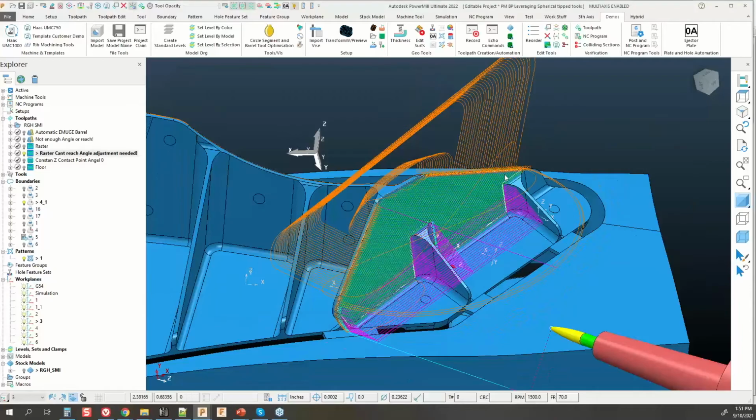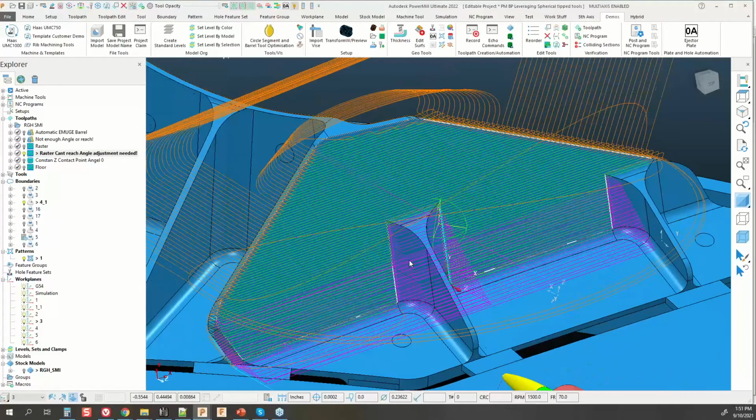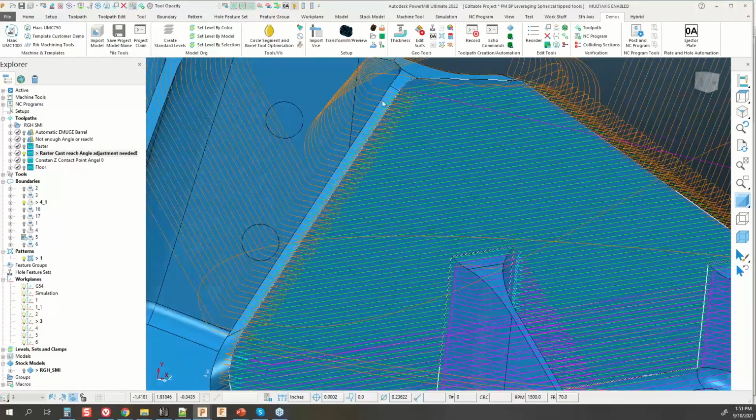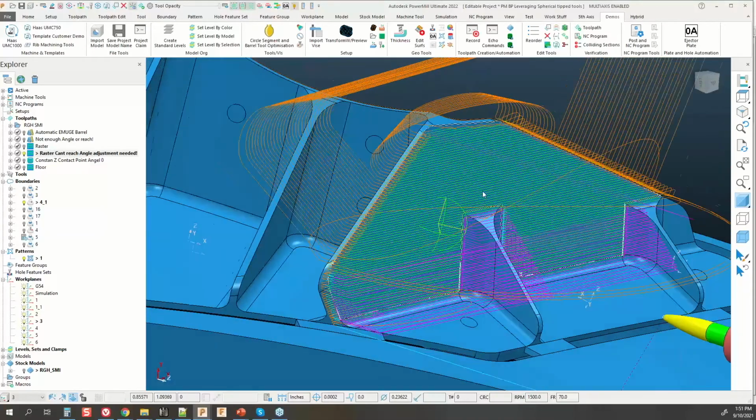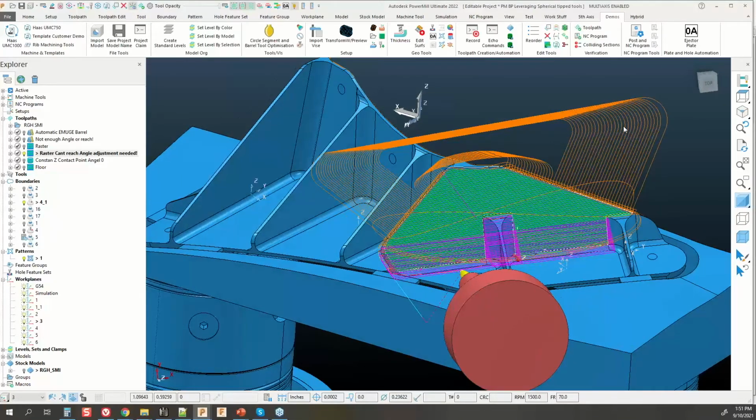Now you'll notice there's a lot of chaff in this toolpath. There's a lot going on here, things that I'm not going to want from the calculation. That's just the raster toolpath finding segments where it's basically reordering the toolpath as it saw fit, and then it's also wrapping just outside of my boundary area. So sometimes when you're using, especially raster toolpath, you're going to get some things that you don't want from the toolpath itself.